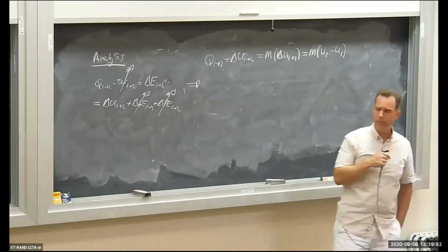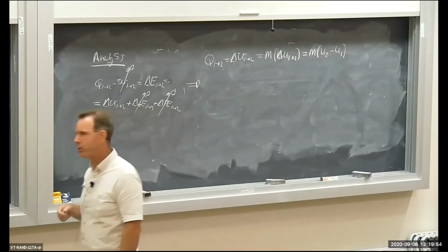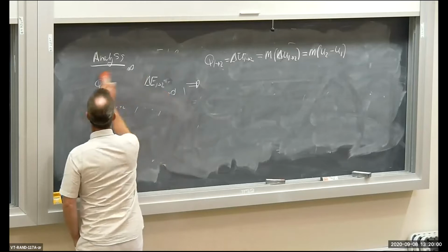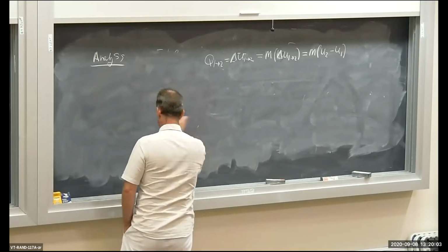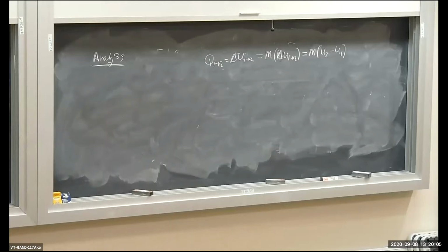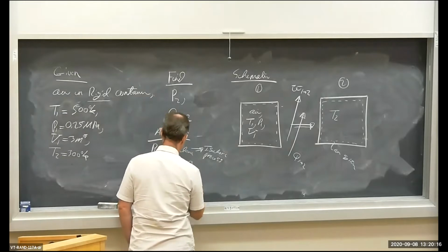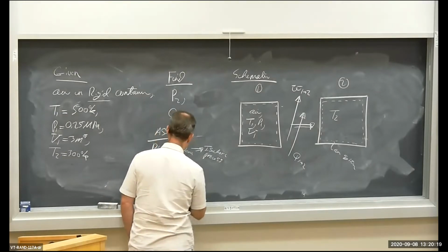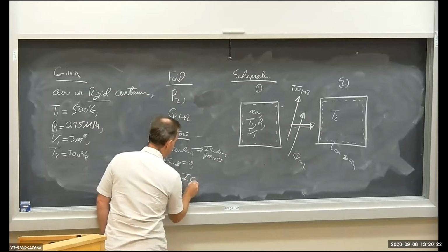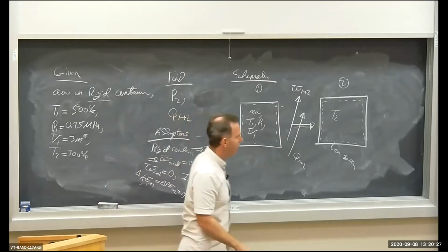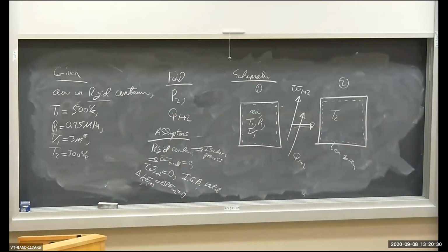I'll tell you what, before we get too far into this, let's calculate the pressure at state 2. I forgot we were supposed to do that. I kind of got ahead of myself. So how are we going to calculate the pressure at state 2 before I do the heat transfer? Well, why don't we assume ideal gas behavior? We can check it if we want. How about we assume the ideal gas law valid? If it is valid, then I can use the ideal gas law.